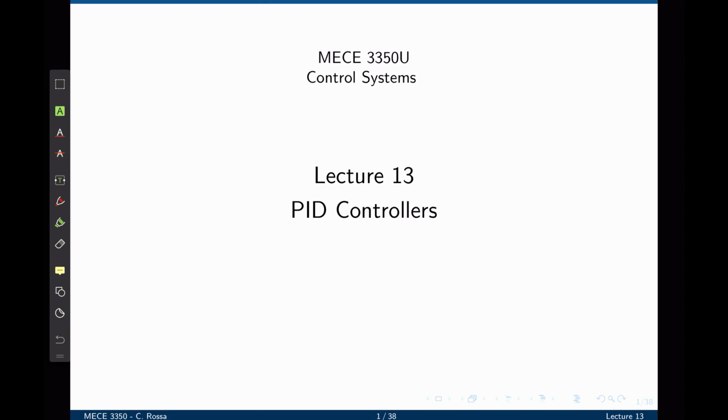The PID controller consists of the additive action of the proportional, the integral, and the derivative component of the error. Not all of them have to be present, therefore we also employ P controllers, PI controllers, or PD controllers. The controller only needs to compute the current error between the measured process variable and the desired set point, then calculate how much and how fast that difference has been changing over time.